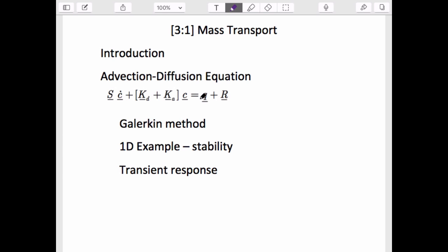Both of those expressions differ from the fluid flow equations in that they have one extra term. The flow equation we've dealt with so far looks like specific storage times a change in head with time, the capacitance term, equal to hydraulic conductivity times the second-order rate of change of head in space.